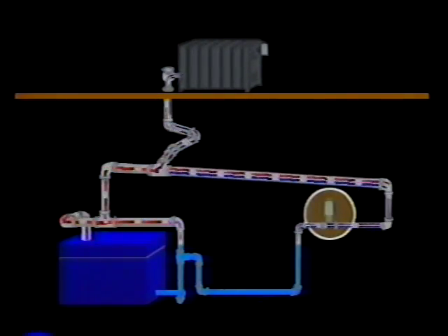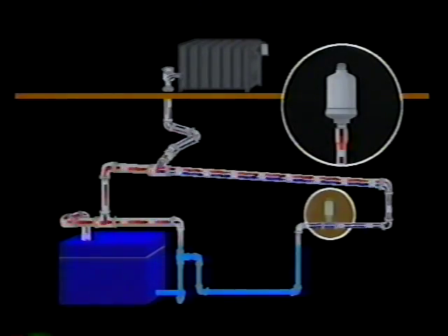At the end of the main, there should be installed a quick vent, sometimes called a main vent. The quick vent rapidly expels air out of the main, allowing the steam to travel faster for more equal steam distribution and for quicker and more efficient heating. Many older steam systems don't have a quick vent or have one that's not properly operating. In any event, it's highly recommended that one be installed or the old one be replaced.